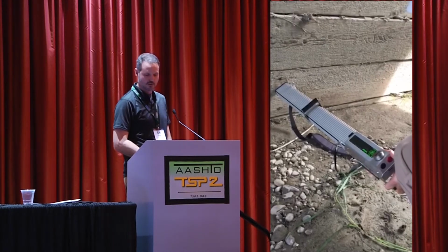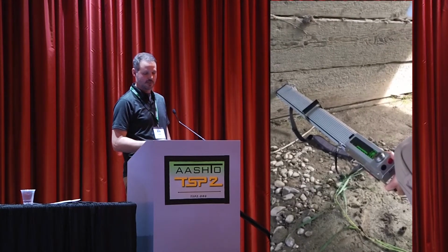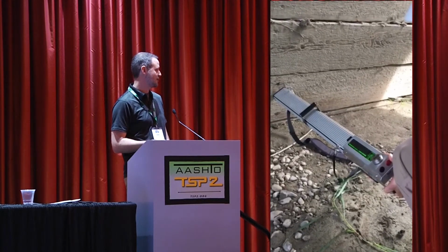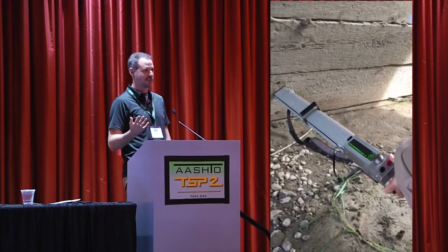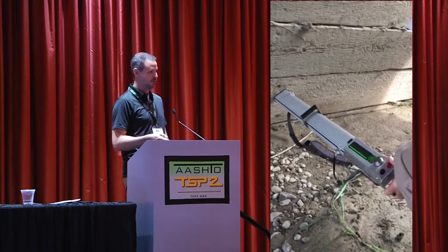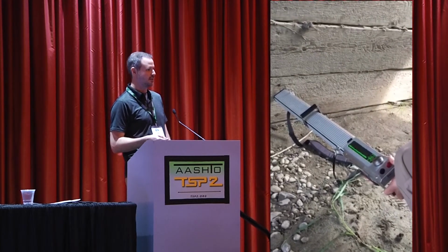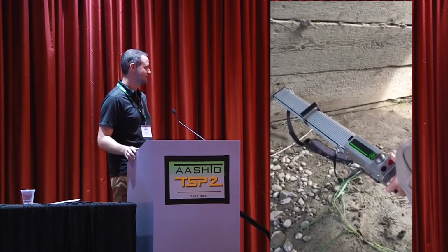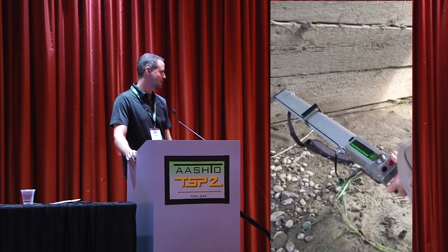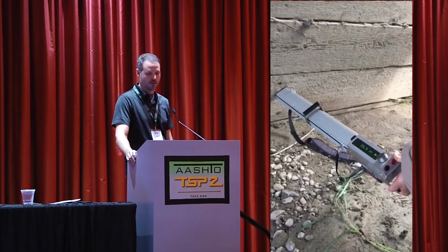But it's pretty fast, as you'll see here in a second. Yeah, so this is actually a video of it in action, and it's not the most exciting thing, but you'll see that this little clip is about 30 seconds long, and that's how long it takes to get one measurement. It drills through the batter boards and the pile behind it. So using the old hammer-all method, you can inspect timber piles that are behind batter boards. So this way you can get some information on those and drill through the whole pile.